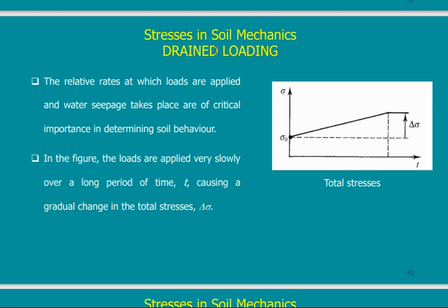Let's study first what is a drained test. Drained, which is similar to sand, means that when I apply the load, water will leave very, very quickly and it will not have any effect. So look at this chart. This is a relation between the total stress and the time.